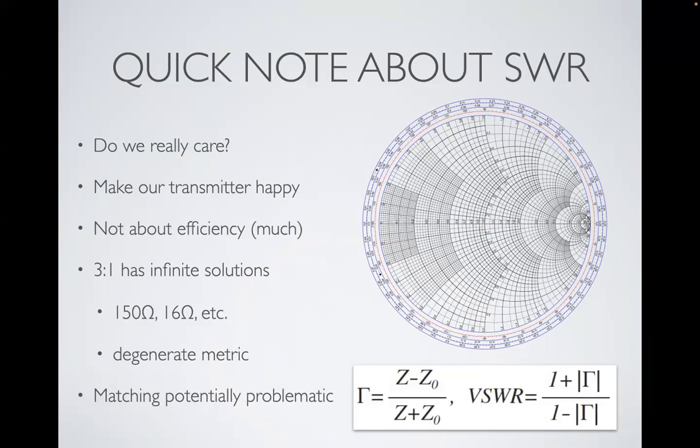I remember one really fun time when I was in Anaheim for a conference, and I was on the roof of a parking garage and there was nobody else there. So I spread out my radials and my short vertical. Usually that thing tunes up very nicely, but it coupled into the rebar, I believe, in the parking structure, and so the SWR was like 3.5 or 4-to-1.